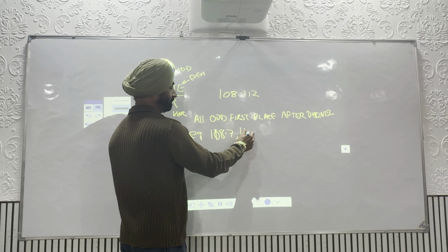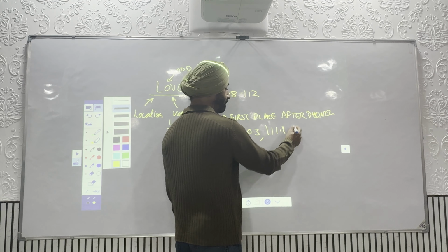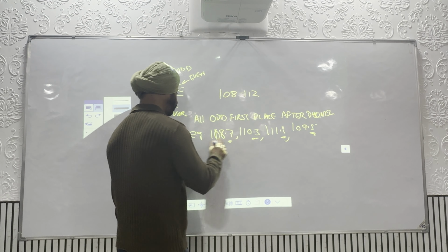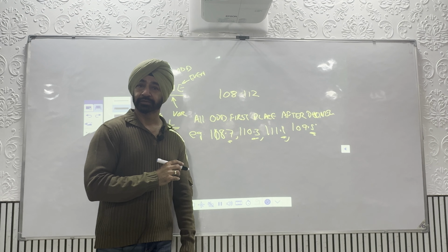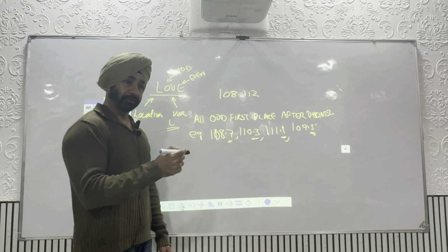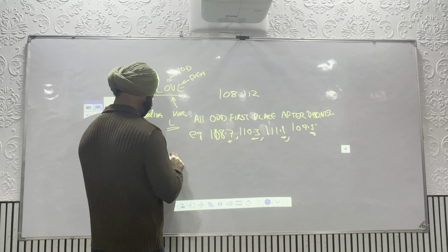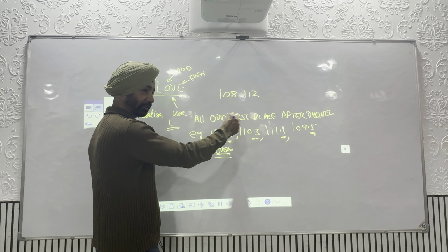108.7, 110.3, 111.1, 109.5. So after the decimal, the first place is what? All odd, that is for localizer. All even first place after decimal are for VOR.